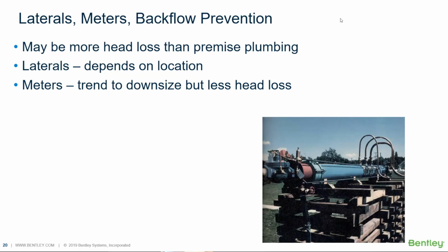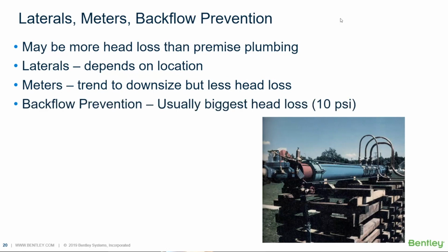And the big one, though, is when you have to do backflow prevention. Now, this is usually the biggest head loss of all. If you're going from the water main into the faucet or your shower, it's the backflow preventer, if they're required in your system, because usually the minimum head loss is 10 psi through a backflow preventer.